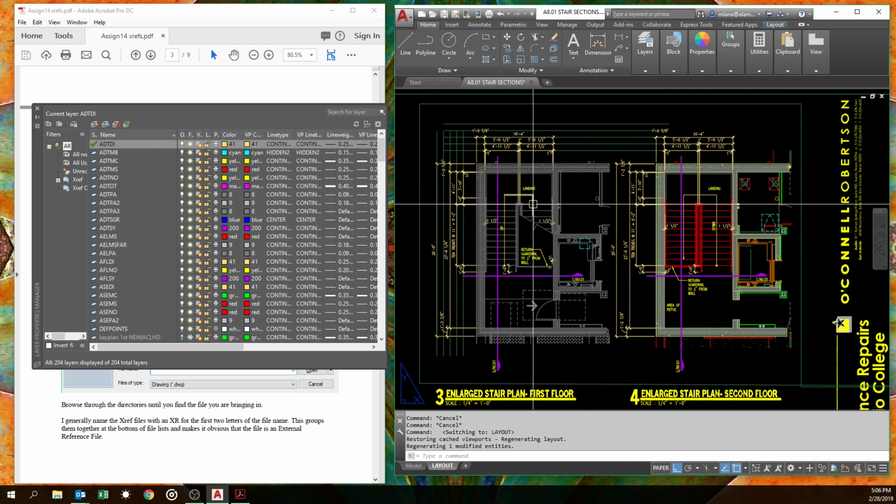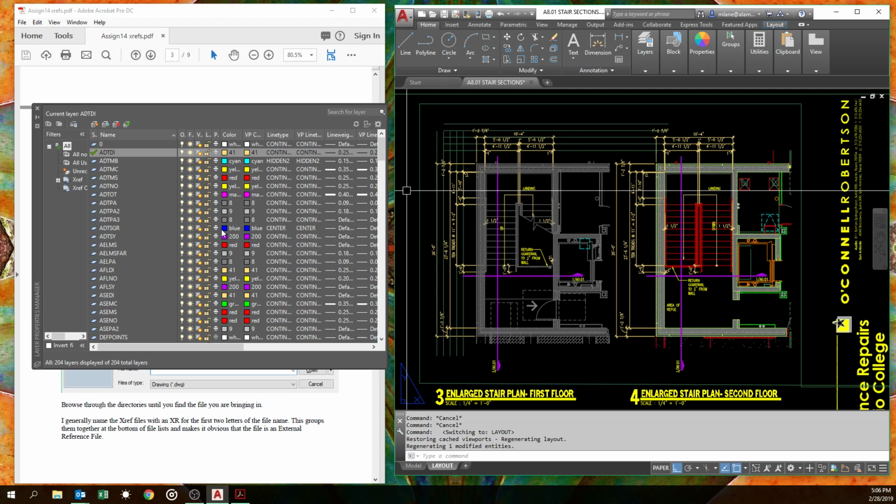It's real obvious when they draw their stuff on top of the base plan, their stuff really pops out because this is all grayed out, kind of faded into the background. So that can be a real useful thing for the consultants. It's also why we try to draw everything by layer, so that's easy for them to do. But anyhow, I had another point I was going to make. Well, anyway, these layers can be manipulated like this, and I have not changed the original drawing. That's just in this file, these colors are now being overridden. And so that's real handy.